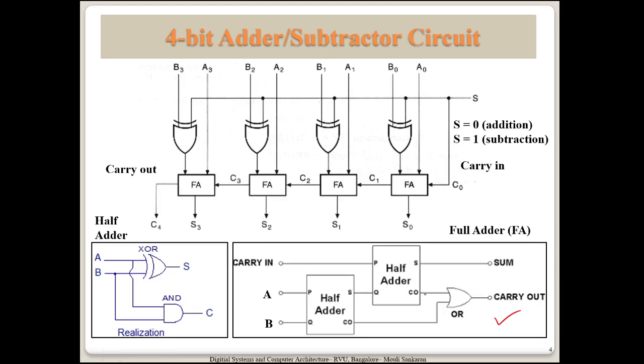So it is enough if you draw this, and inside of it you can mention the gates which you have used in the lab, and then a sample input. Suppose I say 0, 1, 1. Now when I am adding 0, 1, 1, what will happen? The sum will be 0, because if you are adding 1 and 1, the sum will be 0 and there will be a carry coming out as 1. So carry should be 1 and sum should be 0 for this input.